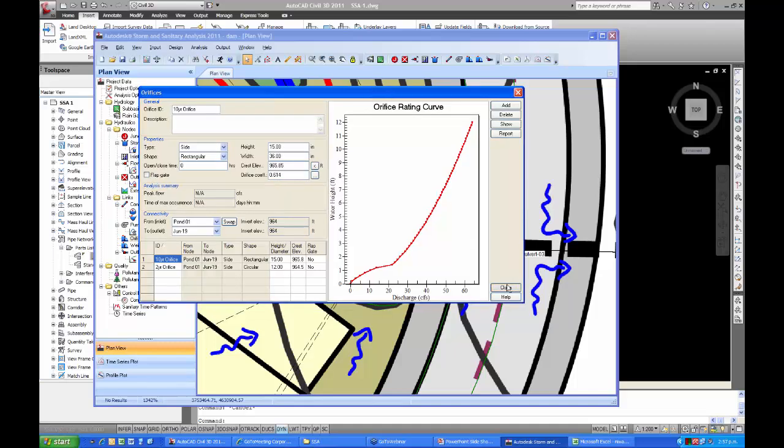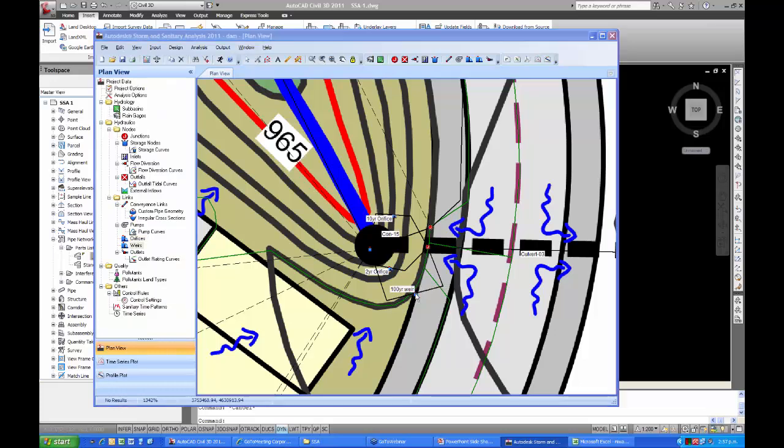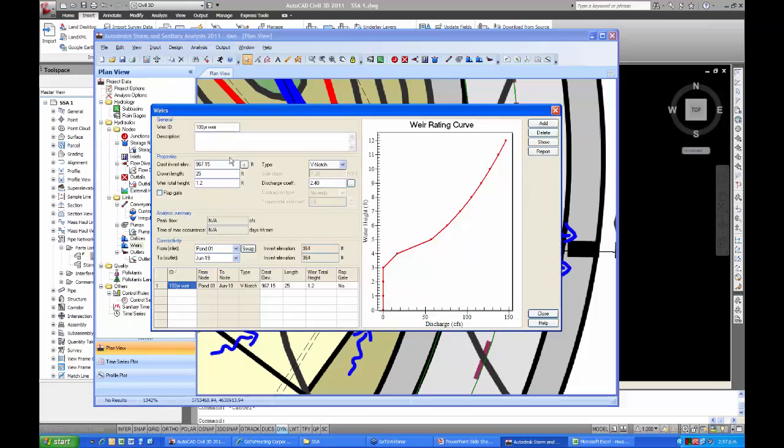And then for the 100-year weir, I jumped in here, and it's obviously not a pipe anymore, it's a weir. You've got V-notch weirs and rectangular, side flow, transverse, trapezoidal, all different sorts of weirs, which basically puts in a different rating curve, and obviously you've got the different variables of crown length, total height, etc. The crest elevation is probably the one that makes the most difference. And that's all to balance the outflow of the downstream pipe.